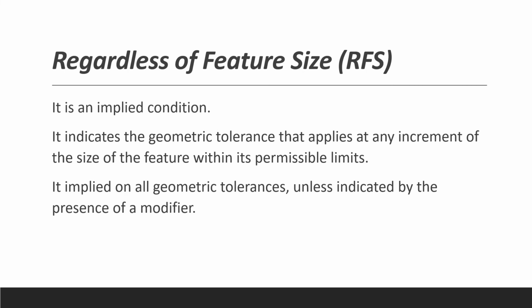Regardless of feature size, RFS. So the material condition, when you think about it, we also have the condition where we don't care about the feature size. It's just implied, we imply that condition. Also, it indicates the geometric tolerance that applies at any increment of the size of the feature within its permissible limits.